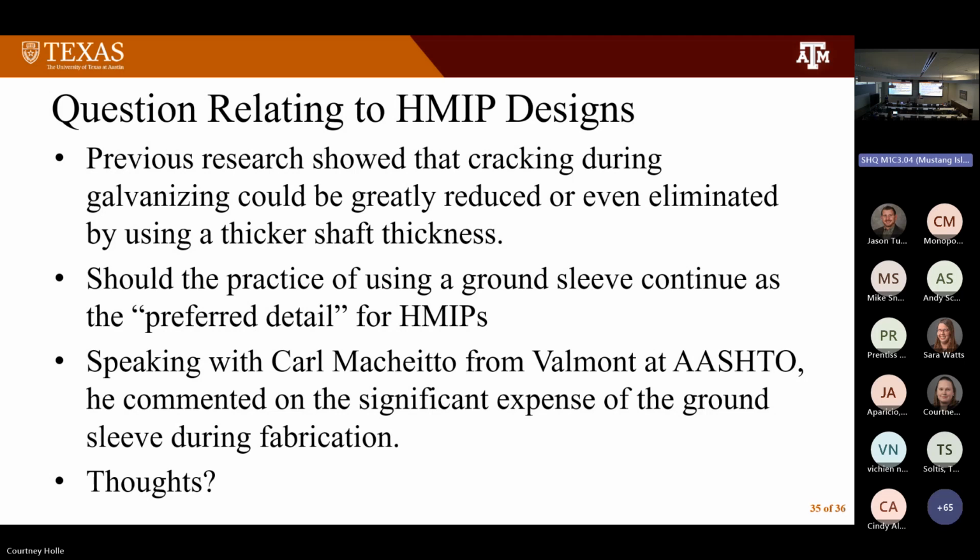Makes sense. And then the last thing is, have you talked with other states that are routinely inspecting all their ancillary structures to get feedback or input? We haven't really reached out to any other states. Historically we've been looking at details. That's where you get high mast poles, they're almost like 50 snowflakes. It seems like every state's got their own little thing. We stand on this leg when we weld, and everybody does things a little bit different. We use a socket connection, we use this, and so they're all a little bit different. But it's not like this state has the problem and that one doesn't. Every state's got some different little effects on these structures.